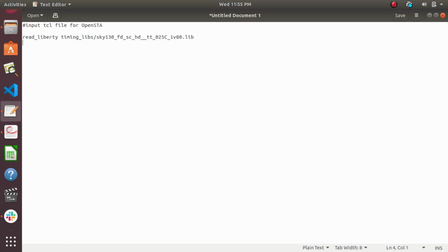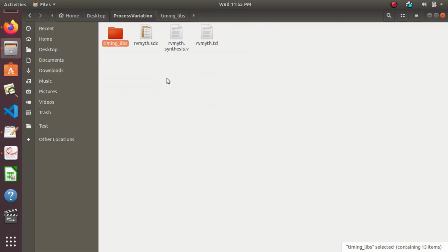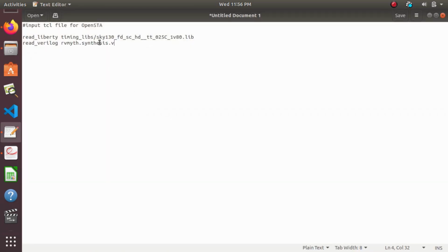And then read_verilog. As I had mentioned earlier, we used the OpenLane run to generate the netlist across the different PNR stages. Now this netlist is also obtained from the OpenLane run, which I have not included yet. This is the netlist after the synthesis. I had already made the Tcl file actually, but still let's go through. Okay, now this is our Verilog file.